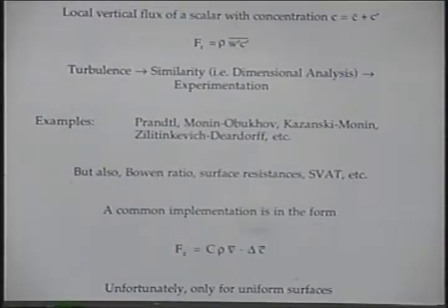Consequently, by the way, I forgot to tell you, at the bottom, you may wonder now, what is a similarity? Well, similarity in simple terms, and all the methods I mentioned a little higher have these features in common, consists of replacing a second moment for the flux at the top of the slide by a product of first moments, namely a mean velocity times a difference in mean concentration, so the product of two first moments.